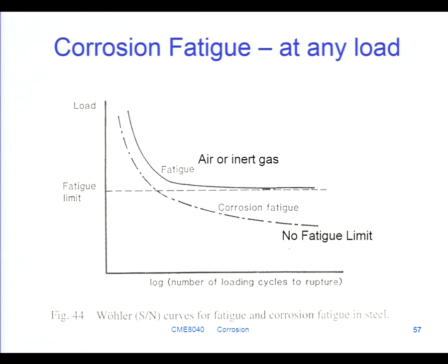Obviously if it's above the yield strength, the material will move and change shape again. And that happens in quite a lot of structures. It's the sort of thing that happens in welding ship plate. If you have a look at a big ship, you'll see that all the panels are slightly bowed because they've been welded around the edges, and the stresses have risen to the point where it actually changes the panel from a flat sheet to a bowed sheet.